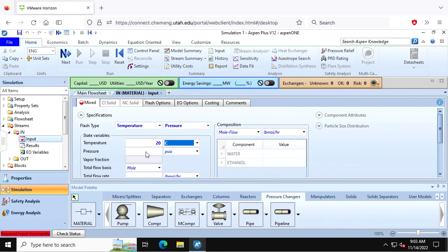Another important number to know. How many feet of water is in one atmosphere? So if you're in a deep swimming pool and you were to go down some certain distance, eventually you get to where the water pressure is 1 atmosphere, 14.7 psi. How deep is that? Let's ballpark it, okay? Is it closer to 1, 10, or 100 feet? 10-ish, okay. Then is it closer to 10, 20, 30, or 40 feet? 30, okay. It's 33.9 feet, call it 34 feet.